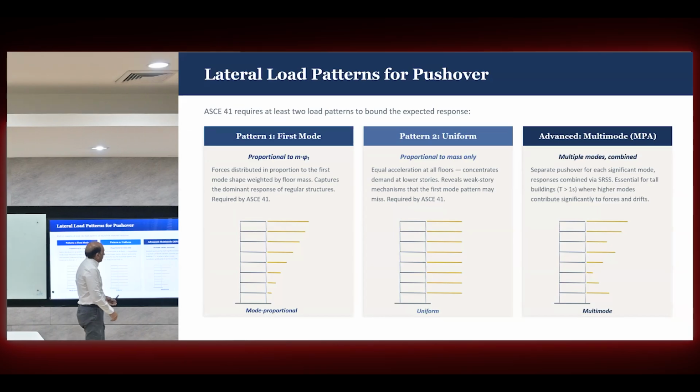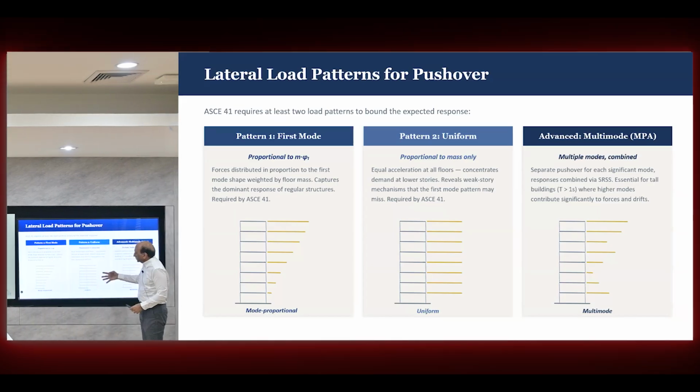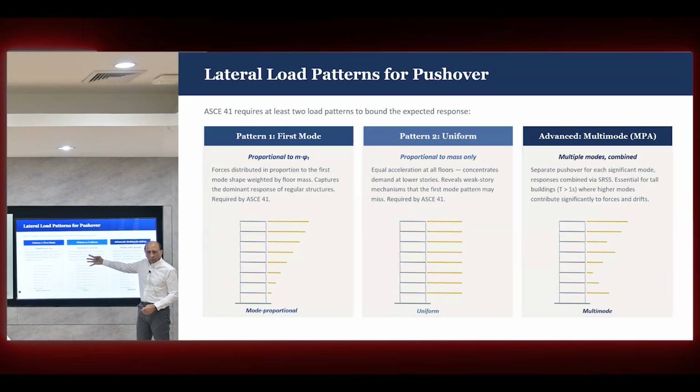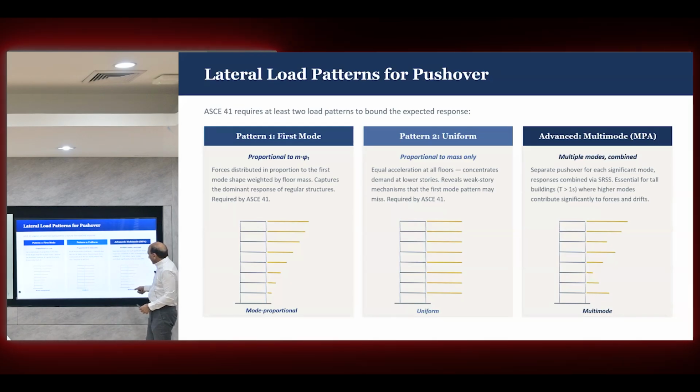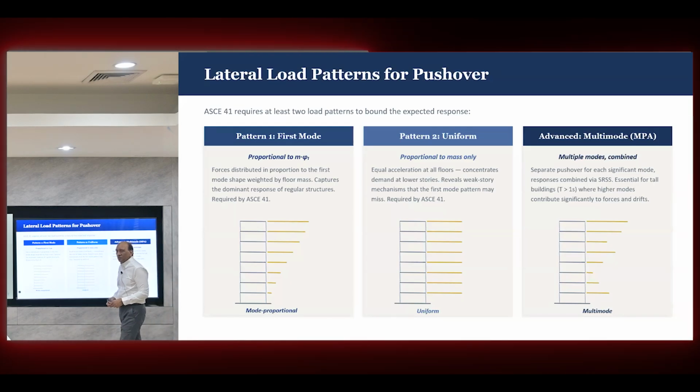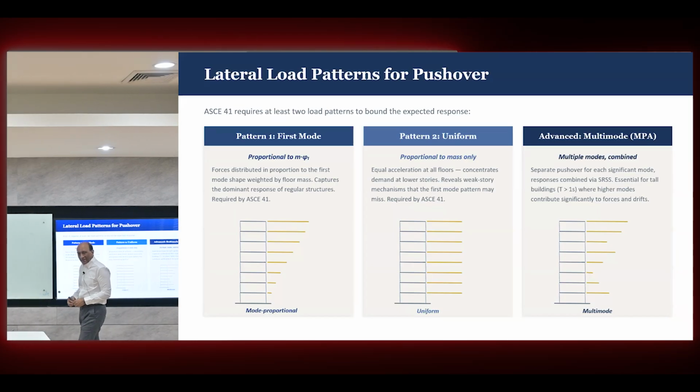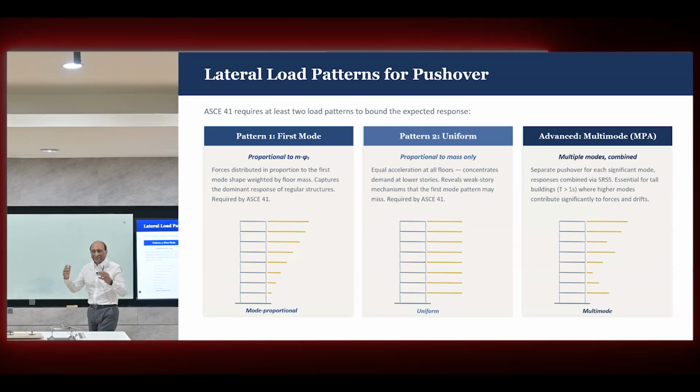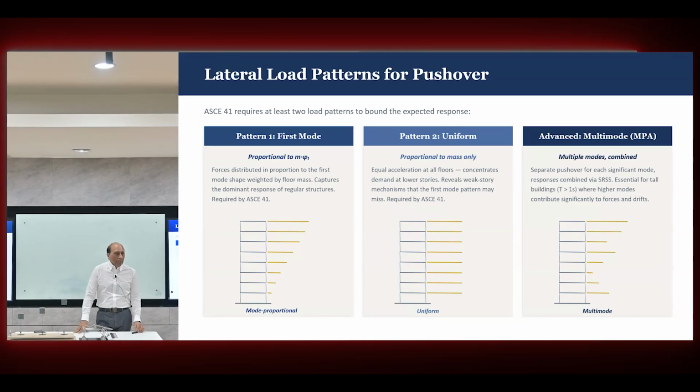Mode proportional, uniform, or multimode. So you also can check the structure for uniform load. And then multimode. That means you check the structure for many modes, one at a time, and then add them together. Because when people started pushover, the first complaint was, what about the other modes?